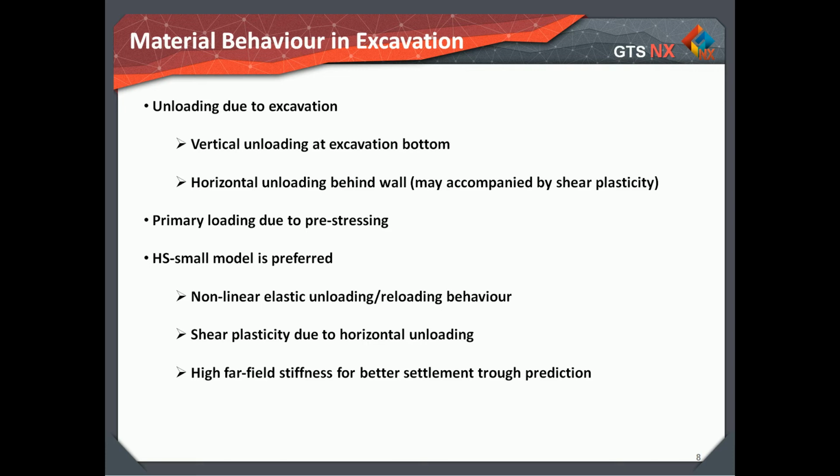The situation is different regarding vertical ground movement. Burland and Hancock illustrate this finding, for example, in their classic paper on the deep excavation at New Palace Yard in London. They assumed a linear elastic constitutive model and were able to predict the maximum measured movement relatively accurately. However, the pattern of movements predicted was inaccurate. This includes a prediction that the Big Ben clock tower would tilt in a direction exactly opposite to that which occurred. Also, the linear elastic model tended to overpredict the movement of the toe of the retaining wall.